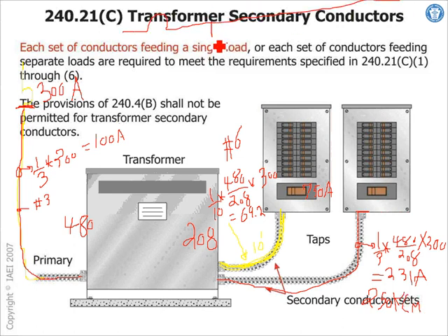I'm making a network, feeding a load here, and another load here from that pole, feeding a third power here. The only condition, guys, is to protect: if this conductor is 100 amp, it has to land in an overcurrent protection device that's 100 amp.